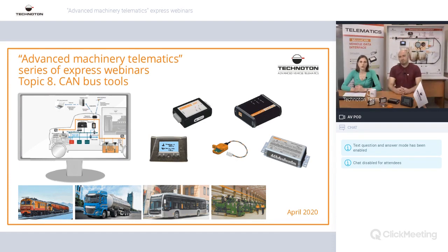Of course, if we are talking about the CAN bus of the vehicle, fuel level is a mathematical calculation of data. When you additionally install fuel sensors, like a fuel flow meter or fuel level sensor, those sensors give a direct measurement of data. And of course, it's more accurate to read data directly from the engine or from the tank itself.